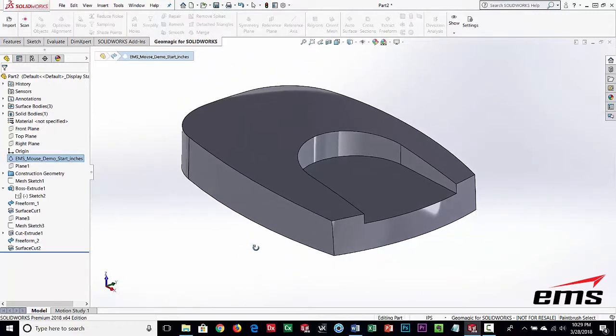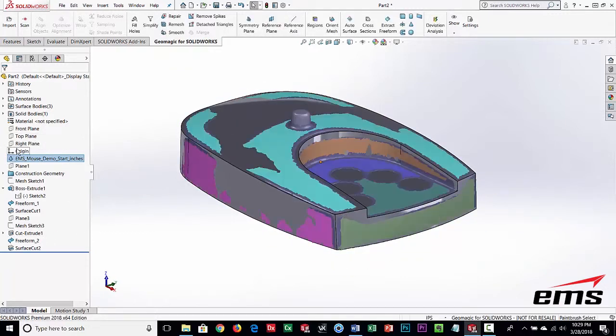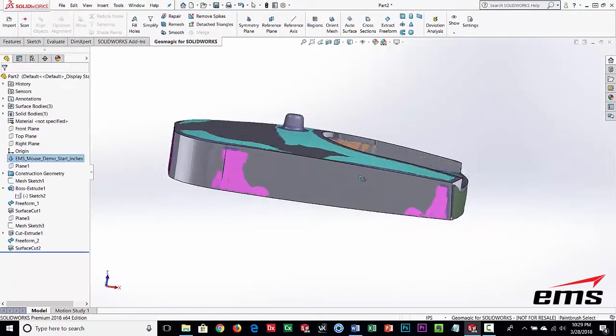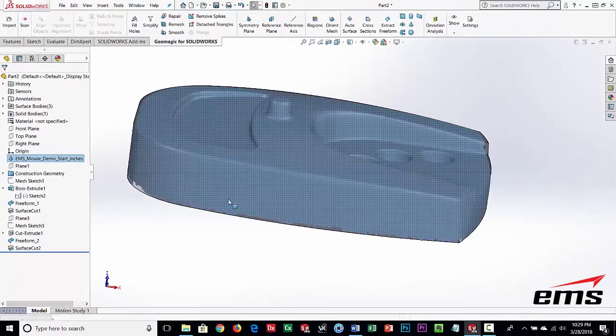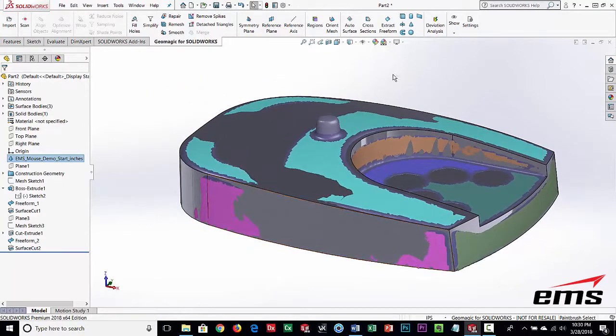Okay. Now I'm going to show one last thing, and then we'll finish this up. So let's go back to the scan data, and on the top here, I've got either a cylinder or a cone, and one of the things we can do is we can extract different shapes from scan data. So a lot of your primitives, spheres, cones, cylinders, planes, even some basic sweeps and rotations you can actually just extract from the scan data, and primarily again those region groups.